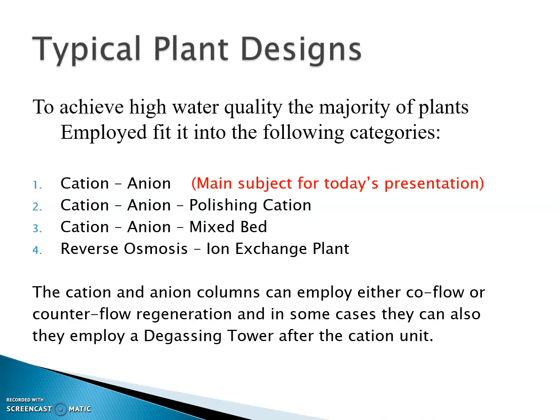Generally, in the demineralization process, softening alone is insufficient for most high-pressure boiler feed waters and for many process streams, especially those used in the manufacture of electronic equipment. In addition to the removal of hardness through the resins, these processes require removal of all dissolved solids such as sodium, silica, alkalinity, and mineral ions. Demineralization of water is the removal of essentially all inorganic salts by ion exchange.